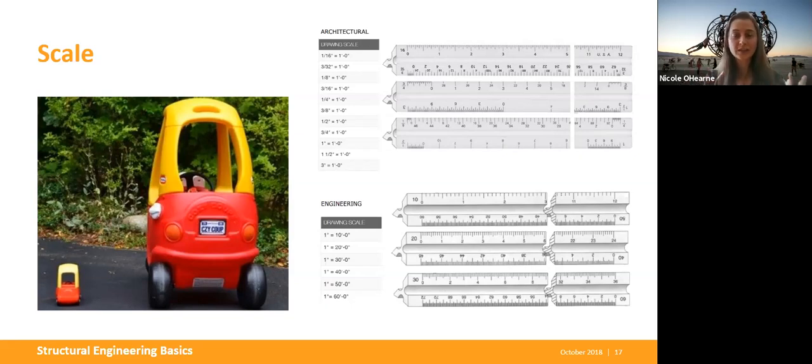So usually the architect will choose what scale. Let's say they're doing 1/8 of an inch equals 1 foot. Then our plans would be that same size, so that when the contractor is going to build it, he can look at 2 pieces of paper, see the architecture plan and the structural plan, and say, okay, this is there, so that means this is there on this plan, and kind of match things.